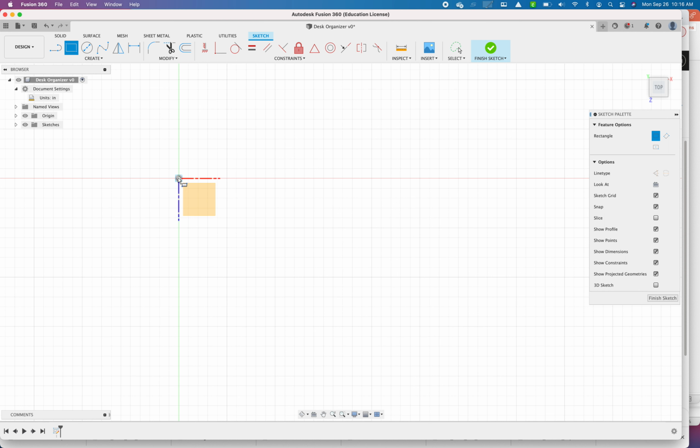If it's not snapping to the point, one more thing that you can change is in your grid lines. You can turn on and off your layout grid, and you can also check or uncheck snap to grid if you want to be able to click on the individual gray grid lines. And I usually just draw something random, and then I am going to make it exact.